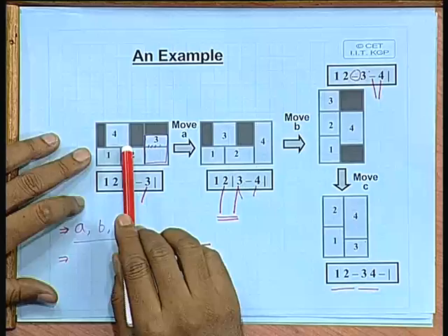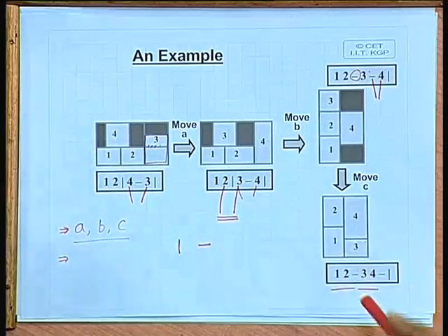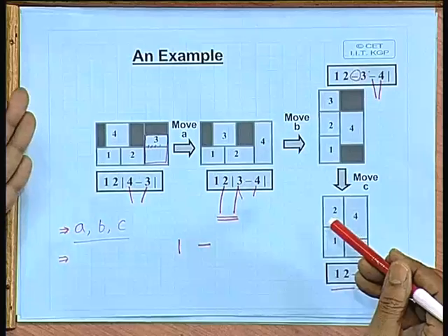First of all, we need to have a graph according to which we will floor plan, because depending upon the interconnects, earlier 1 was not connected to 3 at all directly, but here it is 1 and 3, the edges are touching. See, in this example, just for illustration, we are only looking at the area getting minimized, but interconnection will also come into play.